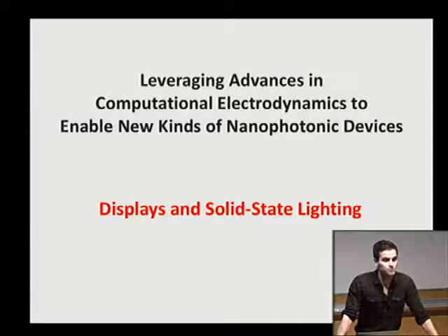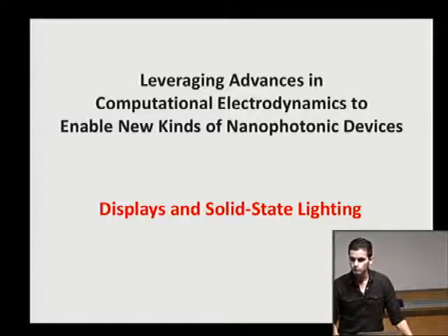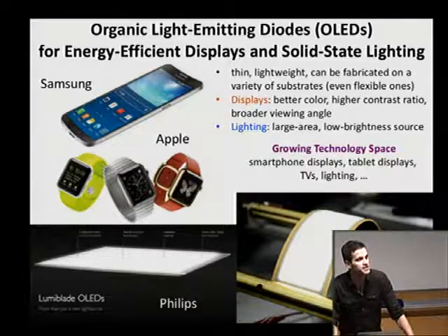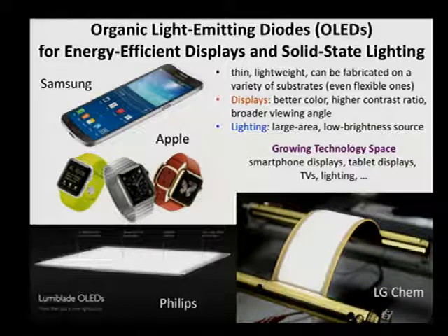Now I'd like to turn to displays and solid-state lighting. One of the key emerging technologies for energy-efficient displays and solid-state lighting are organic light-emitting diodes, or OLEDs. OLEDs generate light from organic molecules and are therefore thin, lightweight, and because of the disordered nature of films of these molecules, can be deposited on a variety of substrates, including flexible ones. As displays, OLEDs offer better color, higher contrast ratio, and a broader viewing angle compared to their LCD counterparts. And for lighting, OLEDs offer large area, low brightness sources.